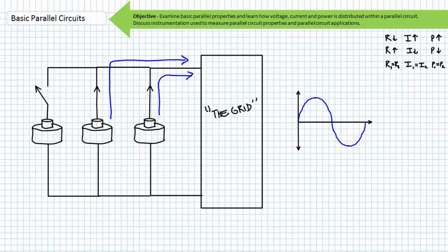Consider a bad day at the dam, however, in which a generator is improperly synchronized with that of the grid. I know we haven't gone into AC yet, but realize AC voltage has a magnitude, a frequency, and a phase shift. And if a generator is to be properly placed in parallel with the grid, it must have the same magnitude, the same frequency, and the same phase shift as the grid at the moment of synchronization. Otherwise, a differential between the grid and that generator will be experienced.